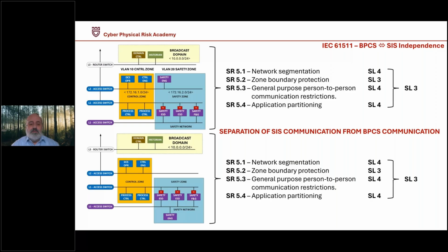It's a separate network, and all the connections between the safety functions go over this safety network. So a safety fire and gas system, which detects maybe fire in some place of the plant, or a dangerous gas, might want to trigger a shutdown of a particular part of the plant, so it signals a shutdown activity.